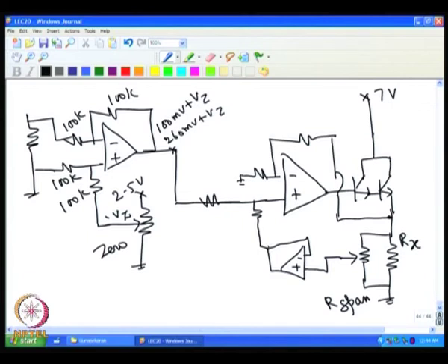The same current source can now be used to get a 4 to 20 milliampere current depending on this voltage. So, for example, here we can have all resistances equal, for example 100 K. For a simpler argument, I remove this and put the thing straight away here.